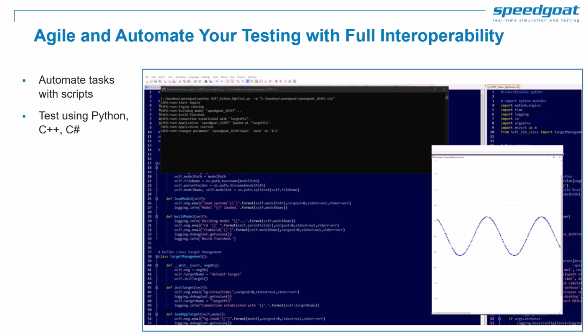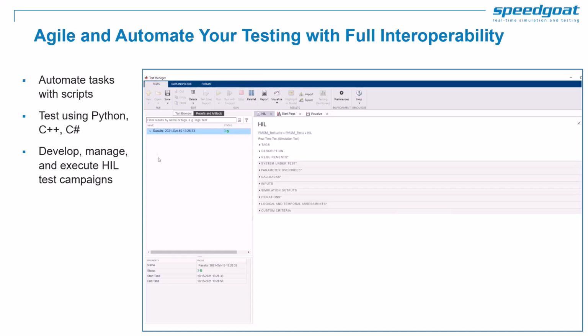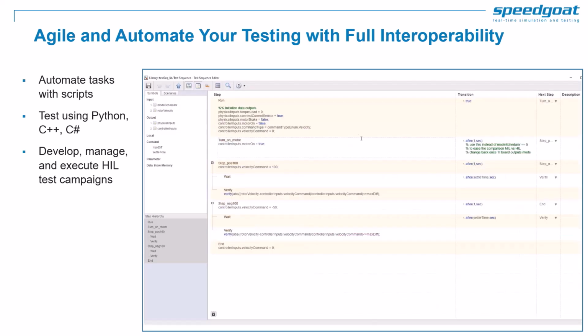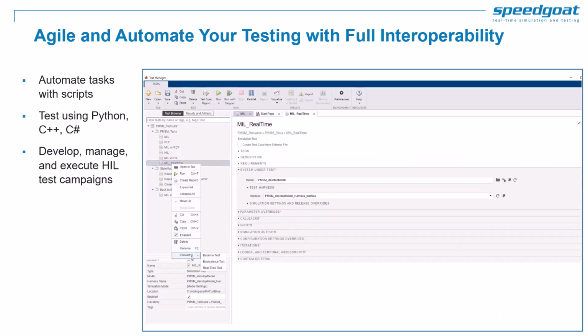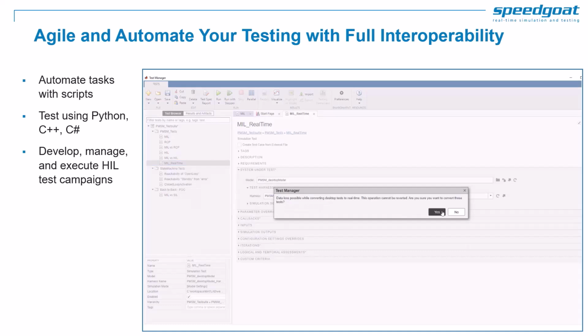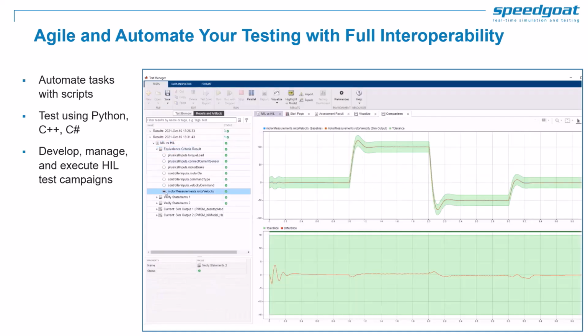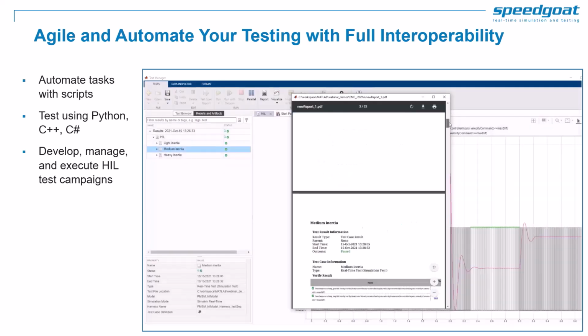Scripting tests can be of great help, but for rigorous testing, you'll need a test automation suite that enables true end-to-end automation. Simulink Test is a great building block within the MathWorks ecosystem that can help you with this. It lets you create and manage test cases, perform requirements-based testing, and quickly create HIL test campaigns for existing desktop simulation test artifacts. The assertion of results is fast and easy using inbuilt visualization tools, and you can automatically generate test reports and share them with stakeholders.